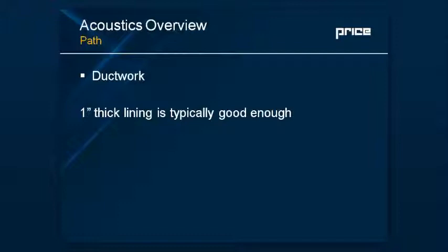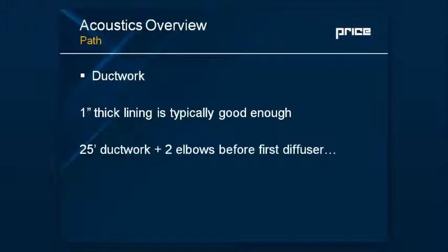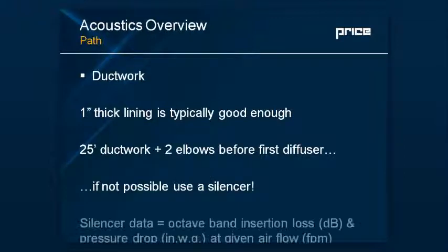And also, if you have a few elbows in there, that's typically more than enough to make up for the difference. Again, a lot of consultants are going to tell you need a certain amount of ductwork and 2 elbows before the diffusers. But again, if you can't do this, then that's where a silencer is often required.